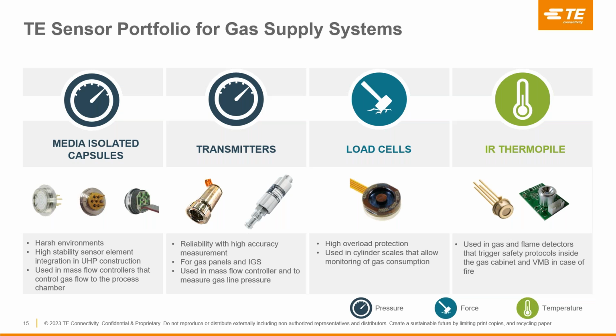This can be configured with a variety of connector options and industry-specific fittings, such as the conventional welded versions, swivel face seals, as well as the W and C seal surface mount types. We also have the capability to offer both analog and digital compensated signal output, either by the use of laser-trimmed resistors on the PCB placed on the back of the sensor, or with our in-house designed ASIC portfolio, which was designed and developed to work perfectly together with our MEMS dies.